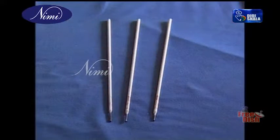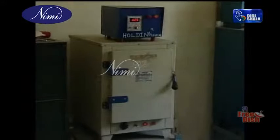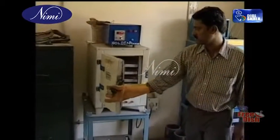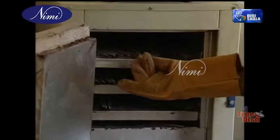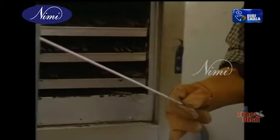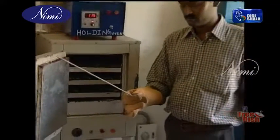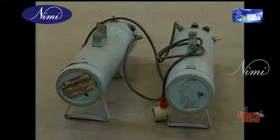Electrodes, especially low hydrogen electrodes, need to be baked in equipment known as an electrode baking oven. Electrodes are placed in trays and heated to 300 degrees centigrade for 2 hours to prevent or remove moisture entrapment in electrodes. After baking is completed, these electrodes are transferred to holding ovens which are maintained at a temperature of 150 degrees centigrade and used for welding at this temperature.